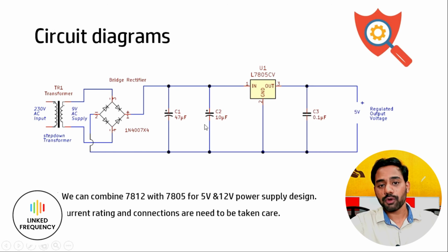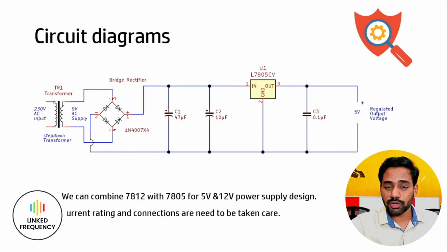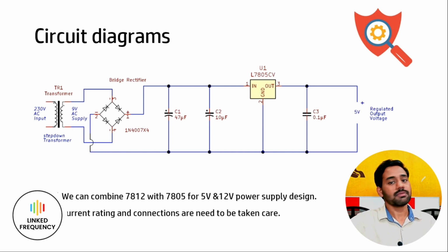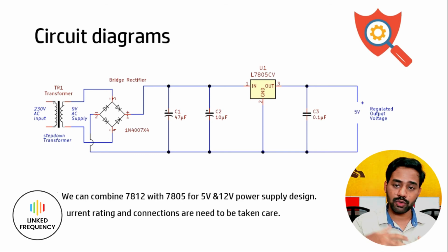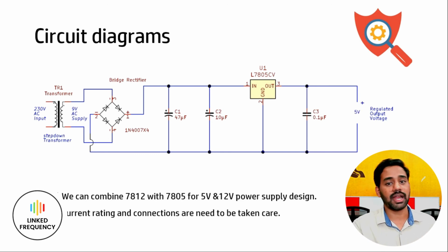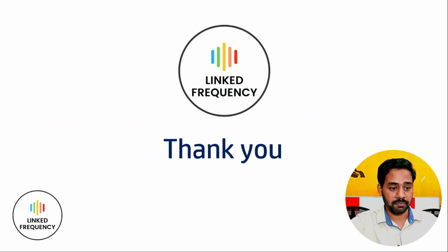Keeping all this information in mind, this is all about your circuit diagram and the kind of analysis that we need to do. Thereafter, what is the next step? It is going to the EasyEDA tool and creating a circuit, referring to the typical application circuit, and then probably starting with a PCB layout and manufacturing files. We are going to discuss those in the next tutorial. But in this tutorial, these are the 5 important steps which you have to cover.